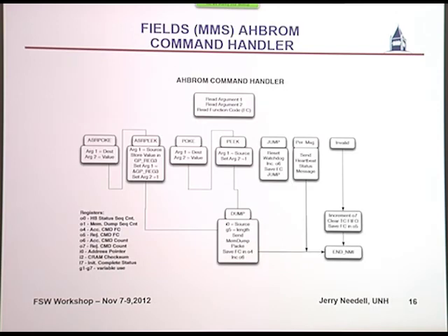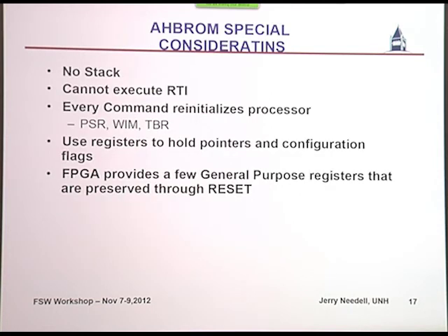The command handler for the fields one is very similar. Peek, poke, and jump, it would take a few liberties. We actually added a few extra commands, but they're all of the same flavor. We got really lazy on this one. We actually added a memory dump, so it's really a super peek, so we could get more than one response back at a time. In a few other cases, there are certain registers that need special handling in the LEON to be able to read. You can't read them with a direct memory access, just a read. You have to do a little extra. So there were critical device addresses, so we added a couple of commands to do that. But the real core is just these three, and it's sufficient to operate the system.